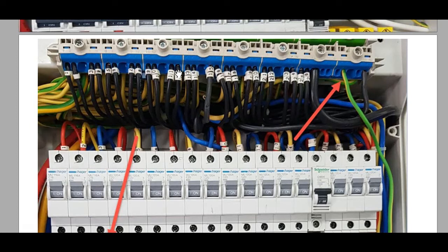Whatever this may be, less than a millimeter or 0.01 millimeter, whatever this flexible distance is, it will cause a loose connection for this panel, and in this case all the neutral wires will be melted, and we are going to a dangerous situation.